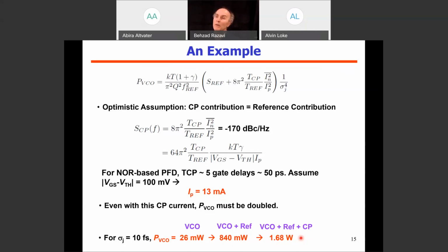So the way I looked at it was that we have a symbol period of 9 picoseconds at the output of the transmitter, and we want the jitter of the clock to be sufficiently small. If we assume that the jitter is 100 femtoseconds RMS, then its peak to peak is about plus minus 400 femtoseconds. And that's roughly what we would expect to hold for proper detection of the signal later. I understand that when this signal is received by the receiver, the clock and data recovery loop will eliminate some of the low frequency jitter. So yes, that 100 femtoseconds is probably pessimistic.